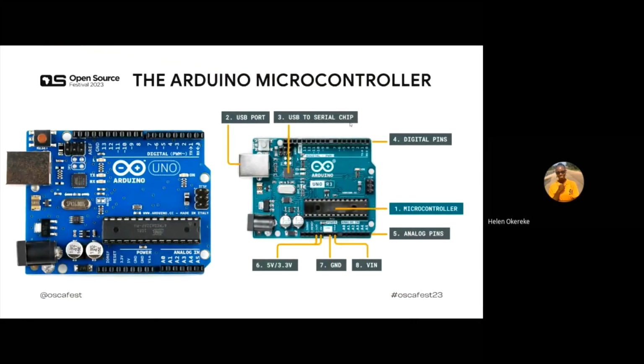And remember, for each of these digital pins, we can only read and write 0 or 1. But for devices like the motor, if we want to read or write something more than 0 or 1, we need these PWM pins. So we have to connect the motor to either pin 11, pin 10, pin 9, just any pin with PWM.